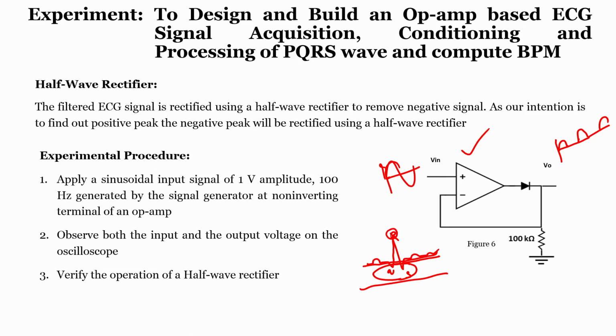The idea is, if we recall what we discussed in the first session of our experiment, if I can set a threshold and find the peaks, the number of peaks above this particular threshold completely gives the number of peaks in a particular duration of time. But why do we have to consider this? The reason is, when we see the peaks, this also will be considered as a peak, this also is considered as a peak. So, if I do not consider the threshold, even these can be considered as peaks, and it is very hard to understand the BPM correctly and accurately.